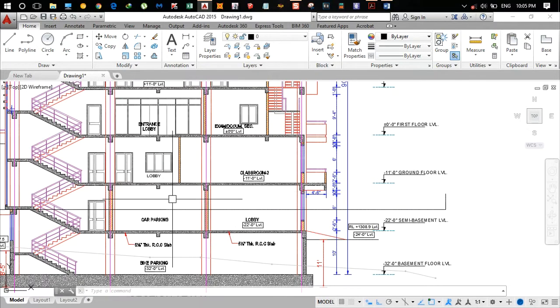Okay, so what we do is that we take half of this portion. That means the half of the columns and half of the walls and all the beams and the slab. So we calculate the weight of all the columns, beams and slab, and take the height of the column and wall as half. Same goes for this floor. We take half of the height of the columns, walls, and we have already taken slab and the beam.